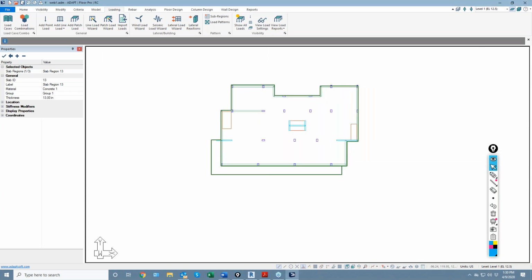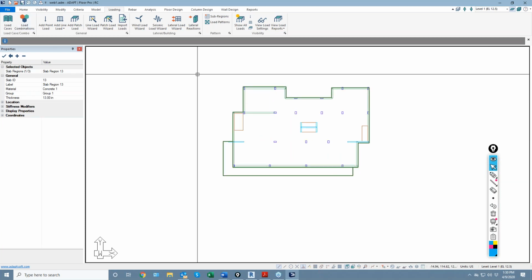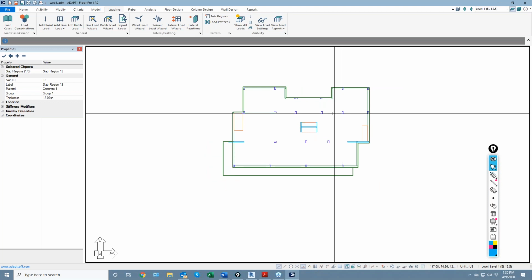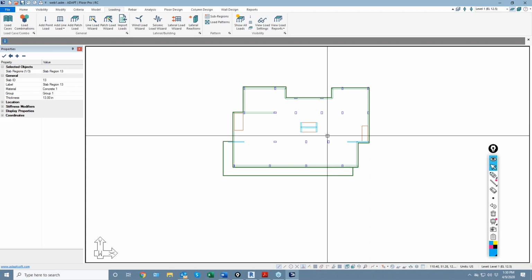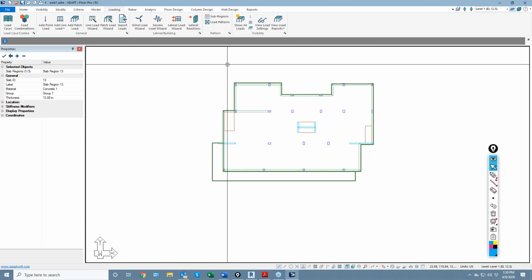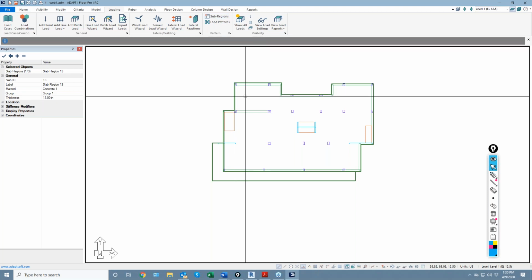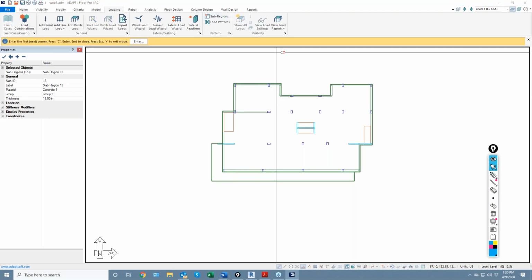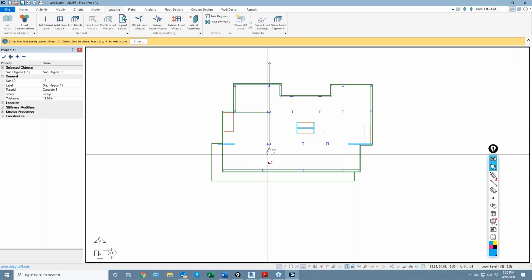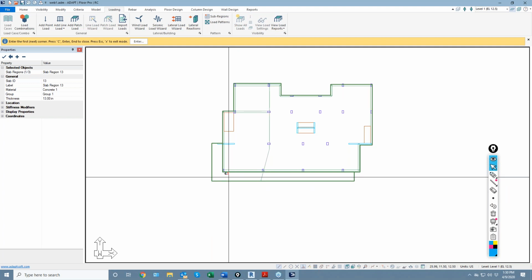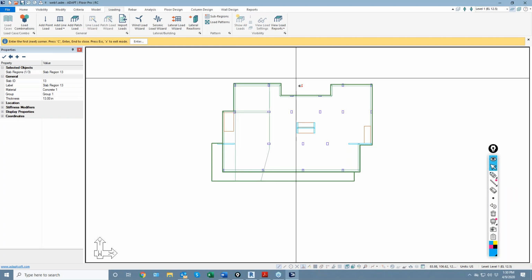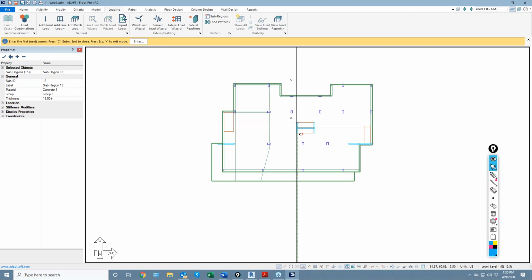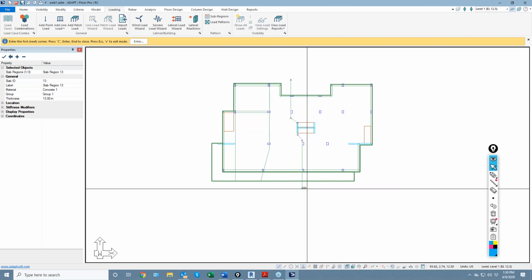Okay, the next thing we will look at is skip loading. And we're going to use just the fully loaded floor, but I do want to show an example of skip loading. I actually just put a video up on our YouTube channel related to this topic that has more detail. But in order to pattern live load in the software, we have to first generate what we call subregions. So I'll just generate subregions based on these dividing lines. We can really just say polylines that we're going to add on the slab. This divides it up into some set of these intersecting zones.